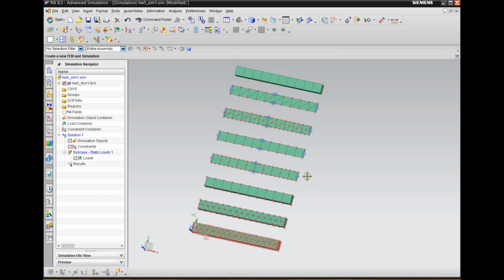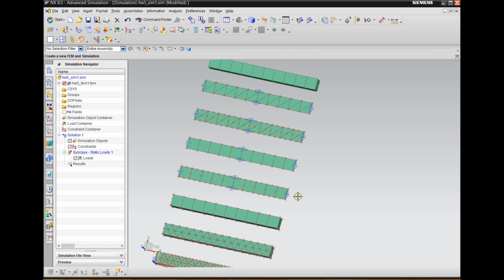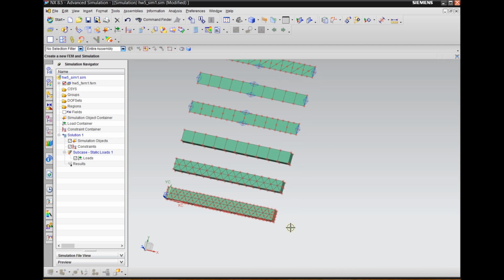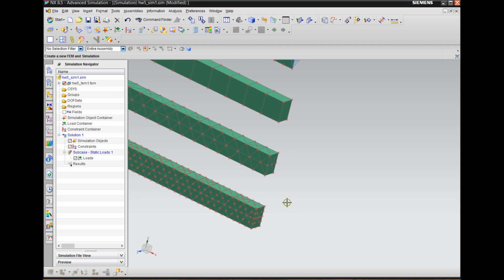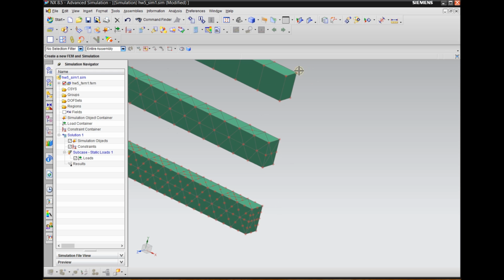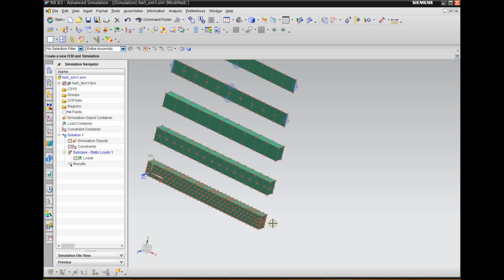So for 1D and 2D, the load goes on one node for each beam. And for 3D elements, we apply loads on the 2 corners. So for a 300-pound load, we apply 150 pounds on each of 2 nodes, here and here.